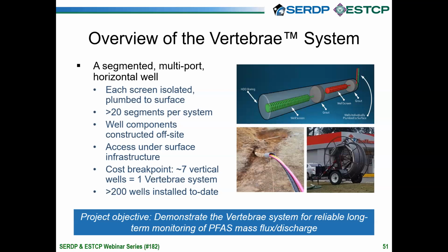And the entire system, including all these screen components and risers, is actually constructed off-site prior to drilling activities. And then it's shipped to the site on these large spools that you can see in the picture on the bottom right. So at this point, it's important to note that because the well is designed and constructed prior to mobilization, you must already have sufficient geologic information to provide the basis for your well design. And also, because the well is installed using a mud-based system, there's very little additional geologic information that's obtained during the well installation.